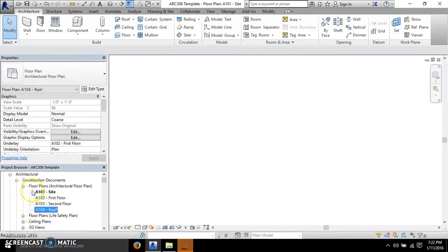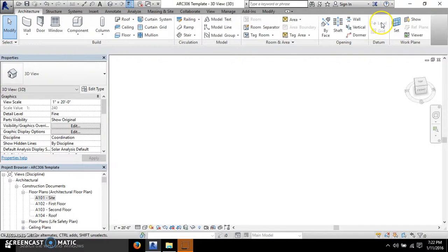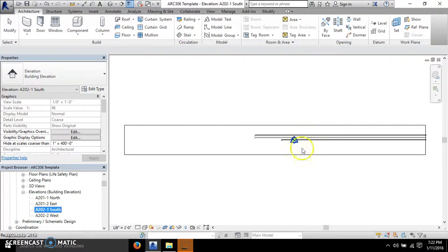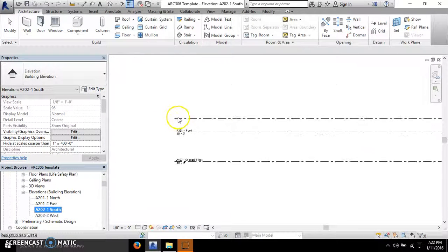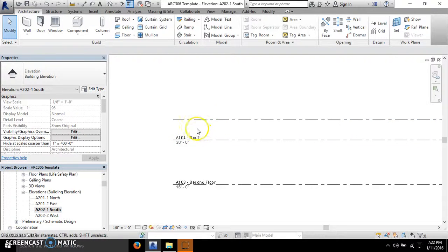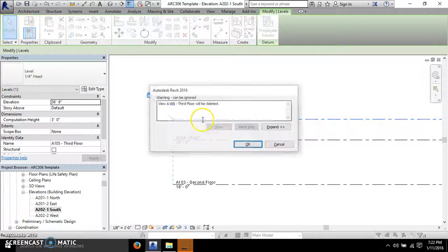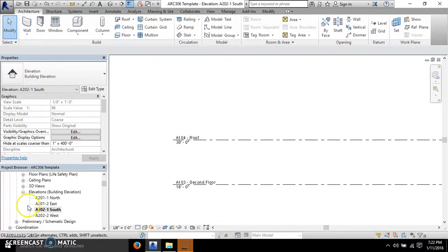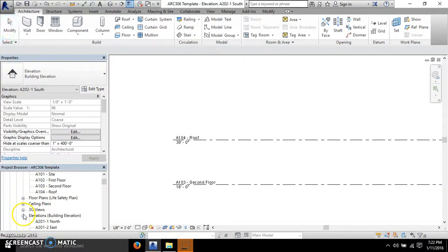And again, those have to be done in either elevation or section. Obviously, you can see, if you're ever in a floor plan, the level is grayed out, and even in 3D, level is grayed out, but if you go into a section, again, you can start to see the actual different levels. That's where you can start to actually see all the levels themselves.